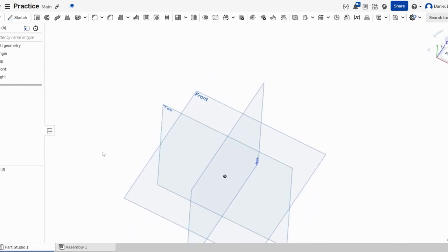All right, now the principle of 3D modeling in CAD, at least with Onshape and most of the programs here, is that we want to create sketches in 2 dimensions, and then we're going to either extrude those to make them 3 dimensional or remove shapes that we want to take away from that object. So those are the fundamental things, or three, I guess: sketching 2 dimensional shapes and then extruding them to make them 3D, or removing parts to change our model. And so let's go ahead and get started.